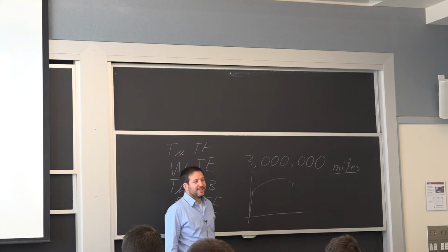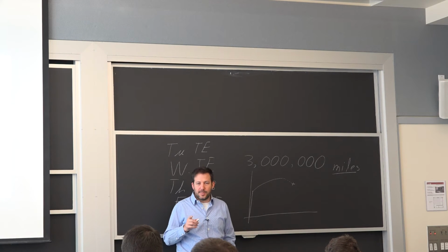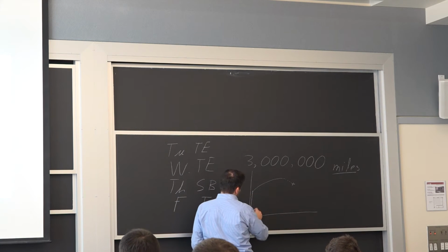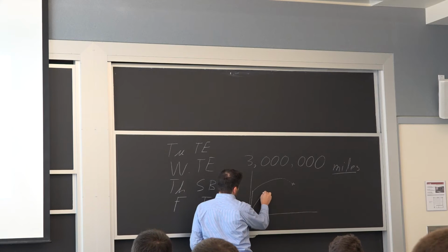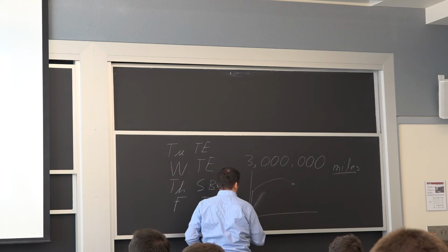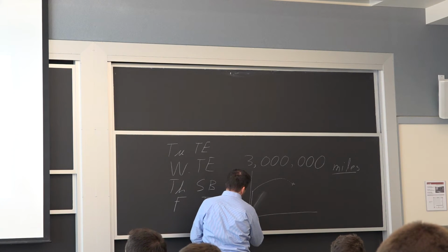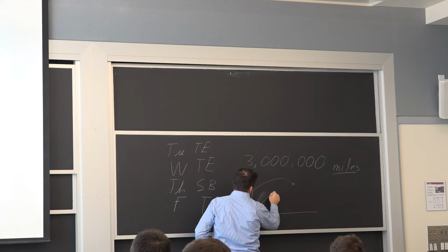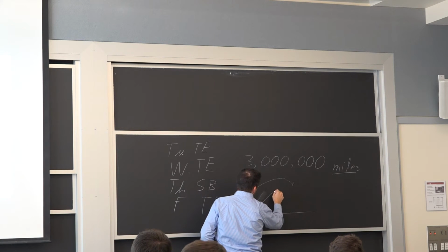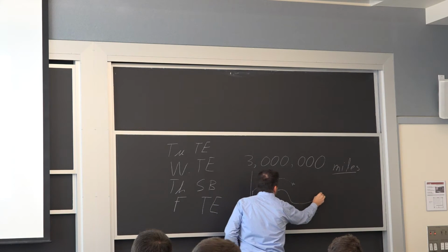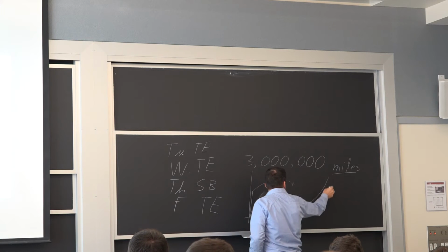Always. So the main difference with the plastic, because of all this super long molecular structure, is you can have a little bit of a similar behavior. So let's just draw it here. It's not quite to scale, so it's actually softer, right? So let's try to get this a little better. So it's much softer elastically. And you can have it at a decent strain. It is lower, but you go up here, you go back down, and you can go back up again. And then it fails right here.